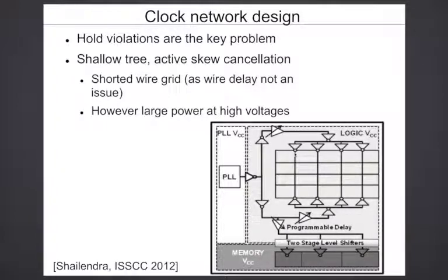Anytime you want to build a wide transistor, you don't build one single transistor with a very large width. You make it up with a number of small width transistors in parallel. That's basically what is happening here. A number of these are in parallel, except they're also spatially spread out. There can be delay between the buffers. So can't there be jitter on both? Okay, so the question is, if you have different delays coming in out here, what will happen to the output?